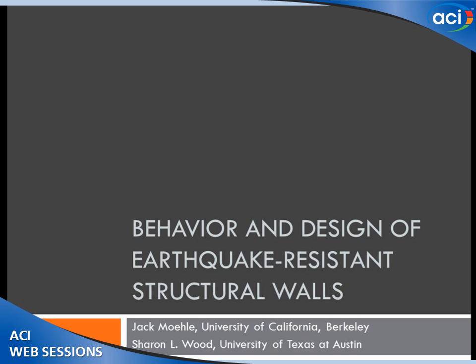If you have a strut driving down the elements, you think of a segment of the wall as a prismatic bottle-shaped strut, that if the vertical steel yields, that strut rotates. And through that process, you see shear deformation coming out of the flexural or the yielding of the longitudinal steel. And those kinds of truss models are capable of seeing that. But I don't know that any of those have been widely used